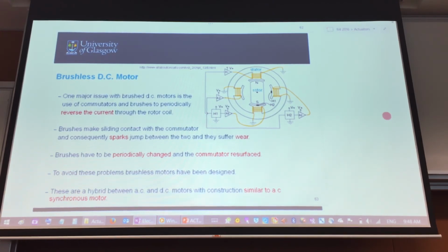That's why cooling is such a big deal. If it can cool down, I can give it a larger amount of power. Your brushless DC motor can accommodate a higher amount of current, and higher current means a larger amount of power. You can squeeze more juice out of it.